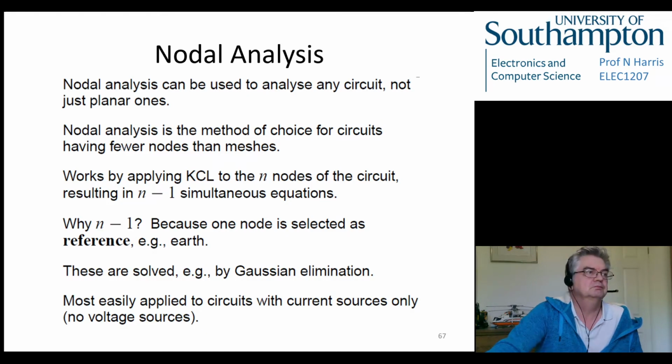So, similar to mesh analysis, nodal analysis can be used to analyse any circuit, not just planar ones. Planar ones, remember, were ones where you could draw them on a flat surface with no overlaps. These are any circuits at all. So nodal analysis is the method of choice for circuits having fewer nodes than meshes.